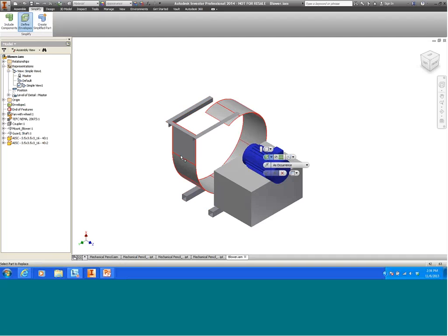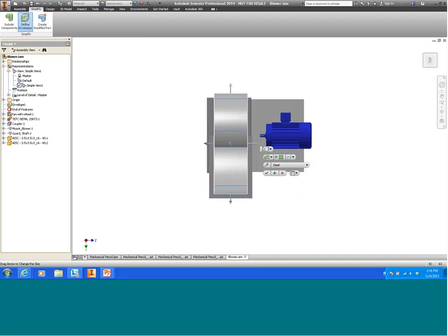I'm going to define my envelope, and I'm going to select the band at the back, and you can see that the band is replaced and previewed with the bounding box. Now, I actually want to make a modification here because I can only select one component to be replaced with an envelope at a time. You can't select multiple components to be replaced by one envelope. So what I'm going to do instead, to be a little tricky, is since I added those other components, I'm going to drag the size of my envelope to cover the outside extent of the model.